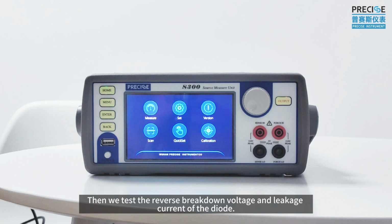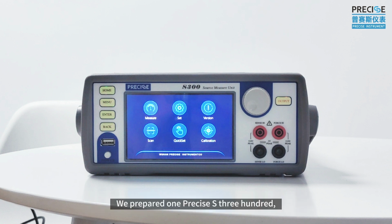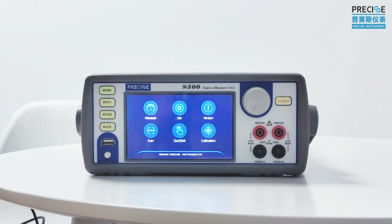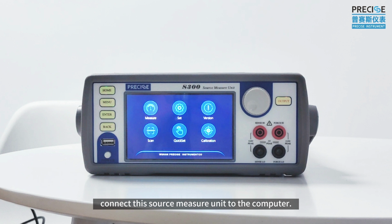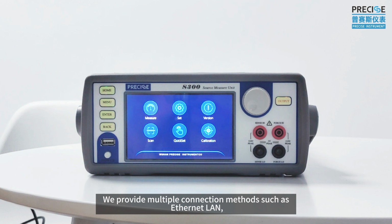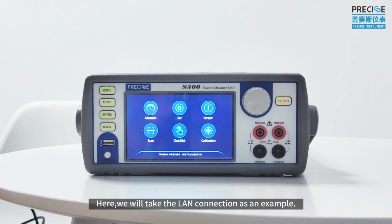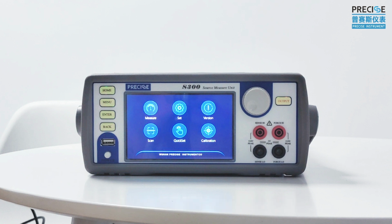Then we test the reverse breakdown voltage and leakage current of the diode. We prepare one Precise S300. Connect this source measure unit to the computer. We provide multiple connection methods such as Ethernet LAN, RS232, and GPIB. Here, we will take the LAN connection as an example.